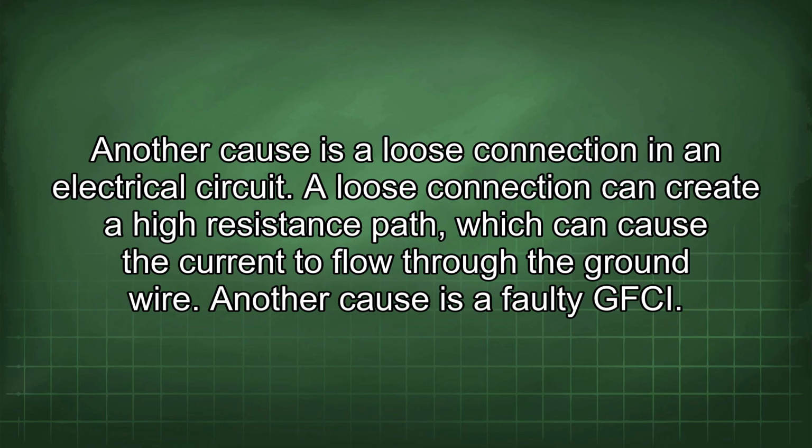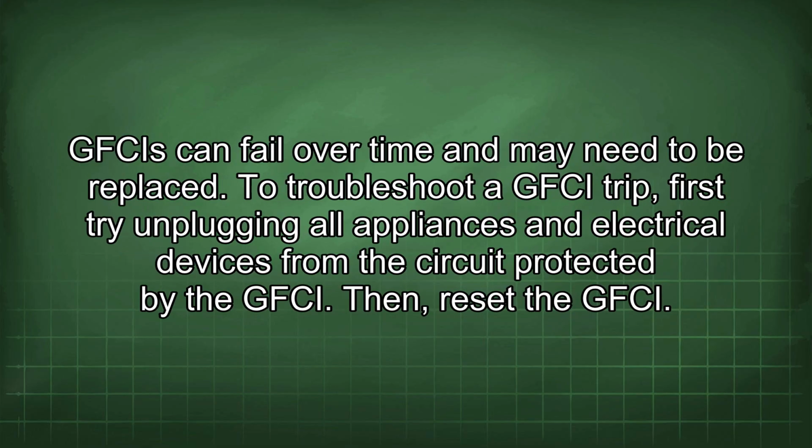Another cause is a loose connection in an electrical circuit. A loose connection can create a high resistance path, which can cause the current to flow through the ground wire. Another cause is a faulty GFCI. GFCIs can fail over time and may need to be replaced.